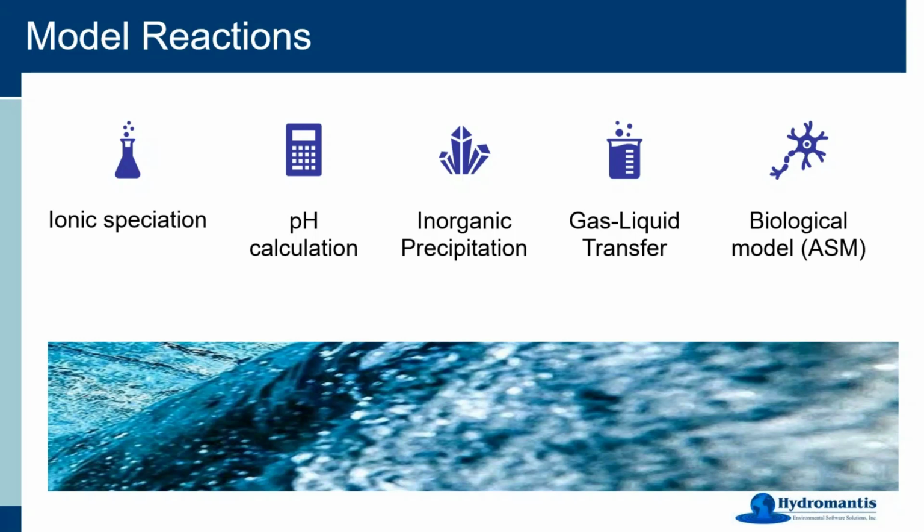So what are we doing here? Basically, we are doing ionic speciation for all the compounds that are dissociated in water. So it's weak acids and weak bases. All of those have temperature dependent dissociation constants in the model, and based on those values we try to identify the ionic speciation in the system. We do a very detailed calculation for the pH, including all the speciation of the ionic species. Then we solve algebraic equations, and we have a very robust calculation method to estimate the pH.